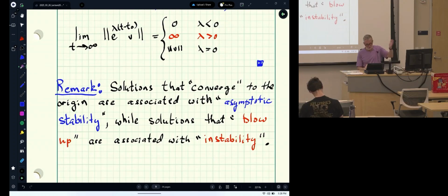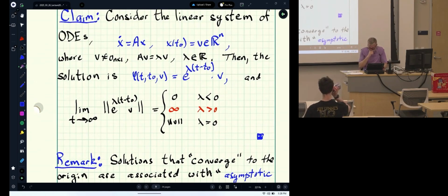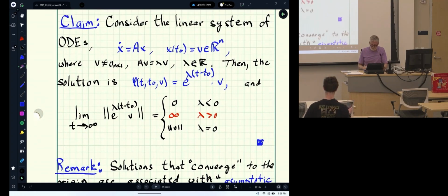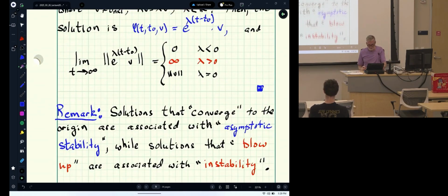Okay, so stability. Stability is associated with solutions that die out when they are perturbed away from an equilibrium. We'll define equilibrium formally, but for a linear system, if it starts at 0, it stays at 0. Put the 0 vector in, e to the At, whatever that is, times 0, that's 0. So it's an equilibrium. You start there, you stay there.